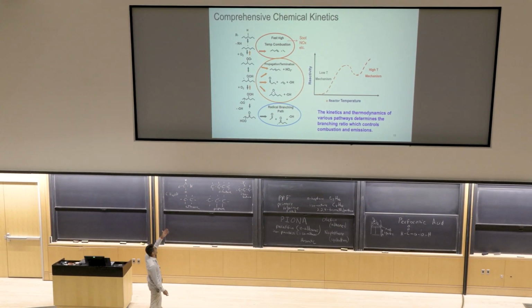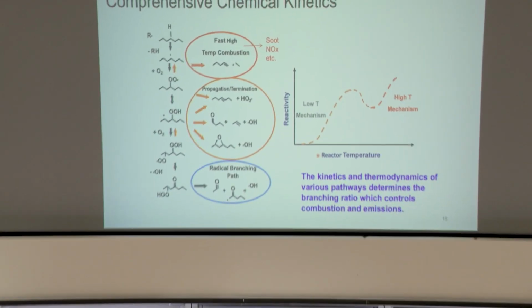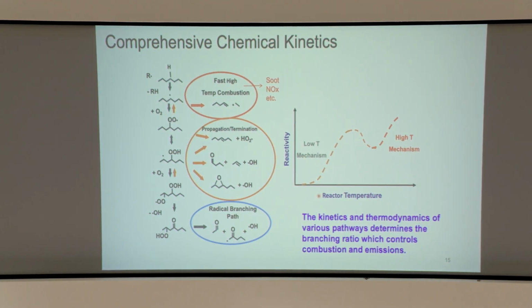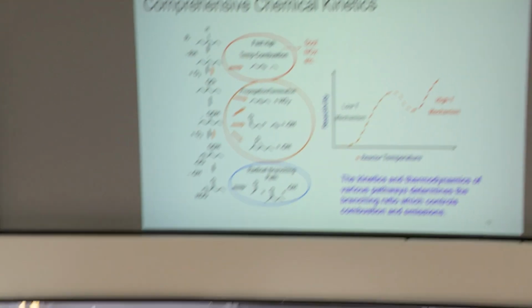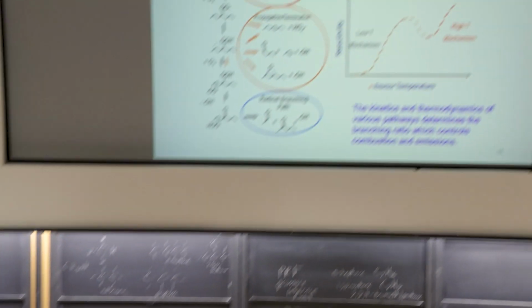Tetraethyl lead cannot. That's why it's very high octane. And we'll talk about this more, why different molecules have different octane. It's because the reactivity in the end gas is different depending on the structure of the molecule. So even in an SI engine, it's important. Ideally, you'll have high temperature combustion in an SI engine, but the phenomenon of knock is a low temperature combustion phenomenon.